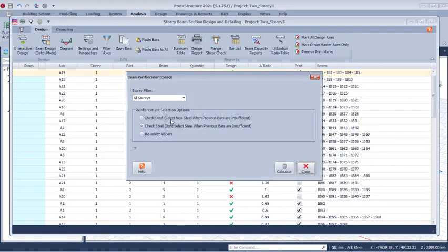So we'll come to this batch design mode. Click right there and then click on select bars, and then click on calculate. It's going to calculate and select bars. If for instance you have analyzed before without checking that the program should analyze and design, this is where you can come and perform your design. If the program only analyzed the structure for you, using the analysis tab without checking the design, you come here to carry out your design successfully, just as I'm doing right away. So let's wait for it to design all the reinforced concrete beams in the structure.